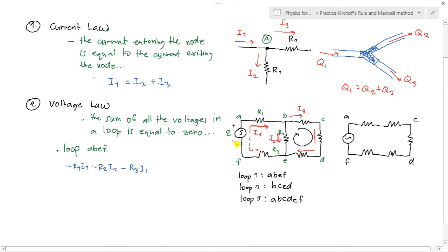Again, don't forget, from earlier, our direction of current is upward. And the sign of our terminals is negative to positive. So if that is negative to positive, meaning from low to high, what is the change in voltage? That is positive. So it is a voltage rise, or voltage increase. So therefore we have plus E, that is the voltage of our source, and then equal to 0. So that is the rewriting of our voltage law. So, understood?